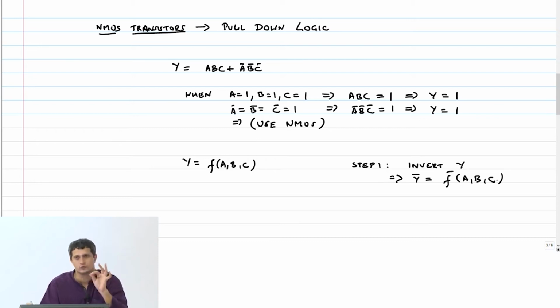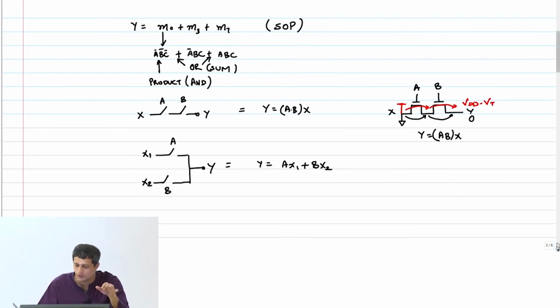We look at what we should do for the PMOS in some time, right? Because I want to get the output to go to logic 0 with the NMOS, but only if I invert will the actual logic be correct. And that's why static CMOS logic is inverting by nature. So you can use the idea that if you put two NMOS transistors in series, or n NMOS transistors in series, you get an AND condition. If you have an OR condition, then you just put them in parallel.